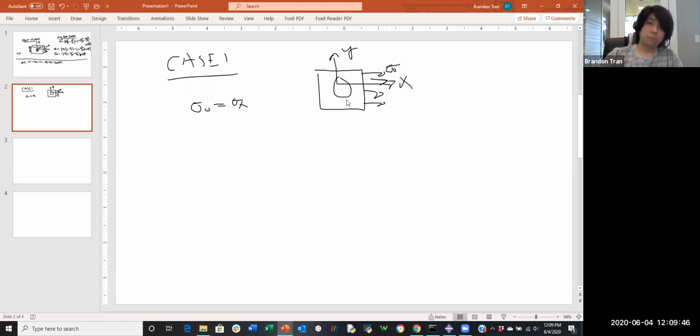So any radial direction you choose, because we have a theta term in this, 1 minus 2 cosine, it's the same equation. You just choose what your theta term is, and you solve the problem that way, and you get your theta stress in the tangential direction, and you can convert that to XY again.